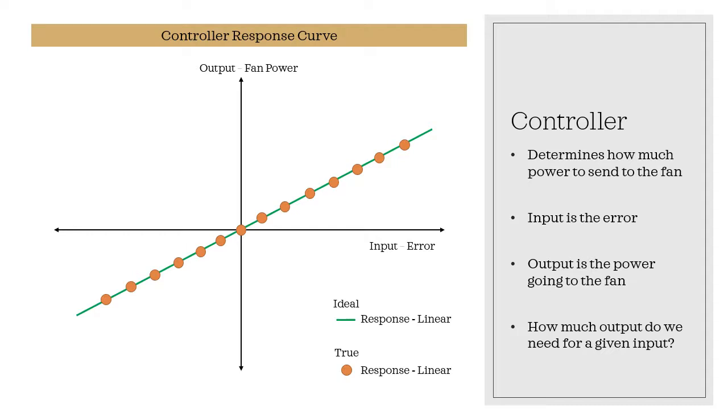So that's the kind of thing you need to keep in mind when talking about a controller and thinking about what kind of controller we can use. For example, the Arduino that we use has potential inputs of 1024. You can take 1024 discrete input measurements. Is that going to be enough for our system? Maybe, probably. It will be in this class. We certainly wouldn't want to design anything that we're incapable of constructing, at least in our labs. But later on, when you're designing things on your own, maybe for your senior project, you're going to need to think about these things without knowing the answer already. If you're doing something that requires a great deal of precision, you may need to find a different way to control, or a way to smooth or interpret the readings so that you can more accurately gauge your output needs.